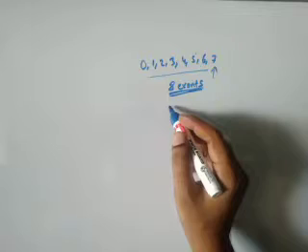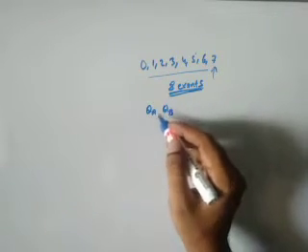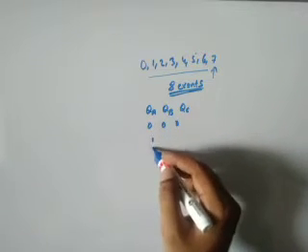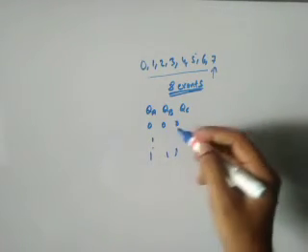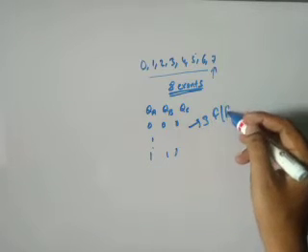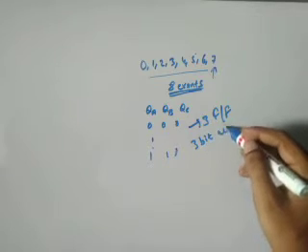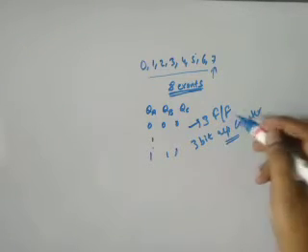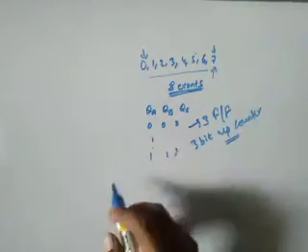For indicating that event, as previously we have taken QA and QB, we will have one more, that is QC, so that the values go from 0 up to triple 1. So how many flip-flops do we require? Obviously we require 3 flip-flops to implement a 3-bit up counter. Why is this an up counter? Because we are going to start with 0 and end at 7.